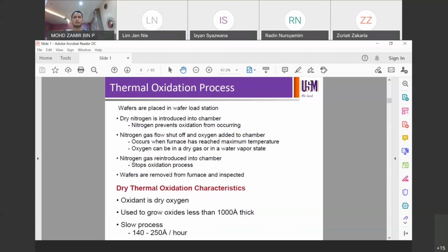And you also need to know whether or not the process or the chamber that you use has introduced particles on the silicon wafers unnecessarily, right? So you might want to know the particle count before the process and after the process, so that you can know how much is contributed by the process, if there is at all.